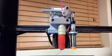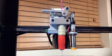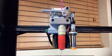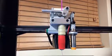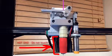When printing or extruding, the small gear turns and the teeth grab the filament and pull it down to the hot end, where it is melted and forced through the nozzle and onto the print bed. Please note, the part of the extruder with the red cover is the hot end, the place where the plastic is melted. When the printer is in use, it is very hot, usually around 210 degrees. Do not touch it.